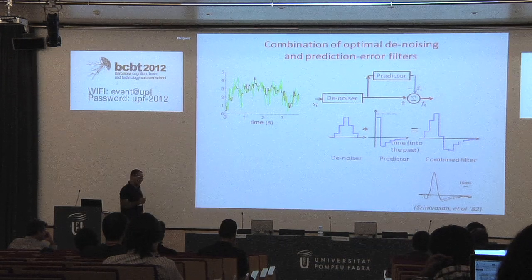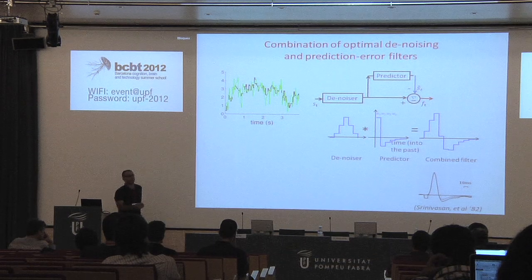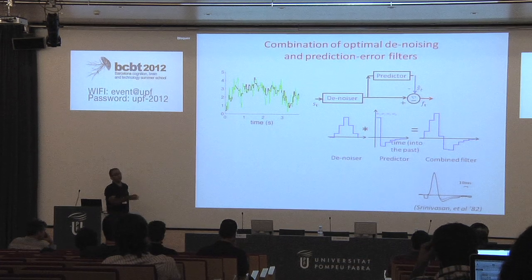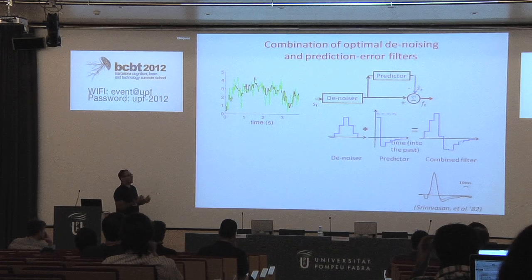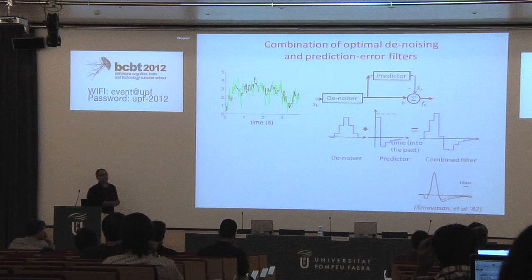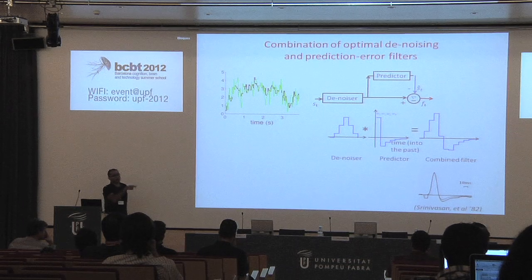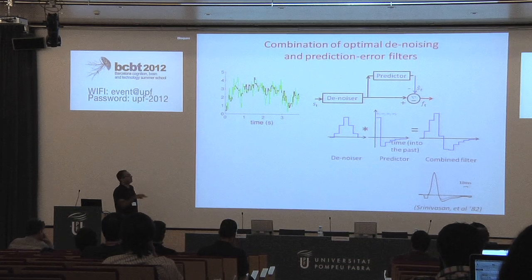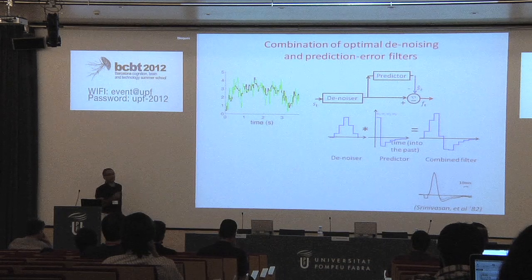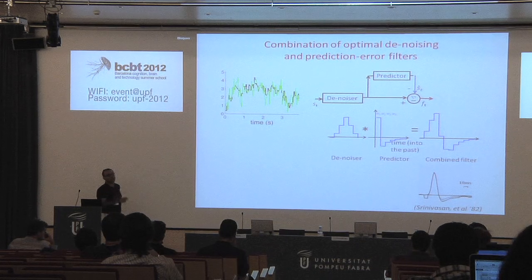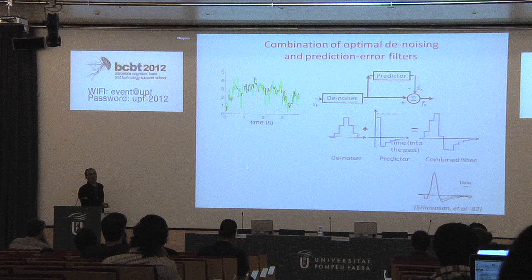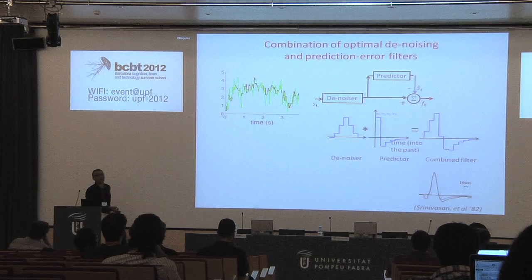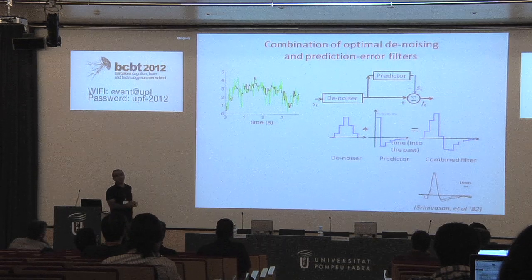And the major component of the noise in their experiment was the photon shot noise, just because at the lower light levels, you cannot forget about the discrete nature of light. The count of photons is integer, and so that introduces noise to the relatively continuous value that is determined by the reflection coefficient of the objects. And that is the kind of noise, the amplitude of which you can figure out from the intensity value. So you can, in fact, know what it is.